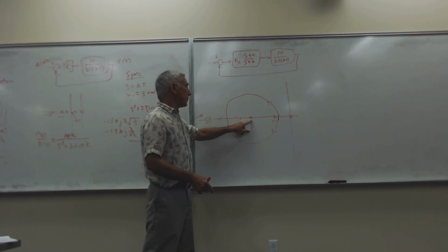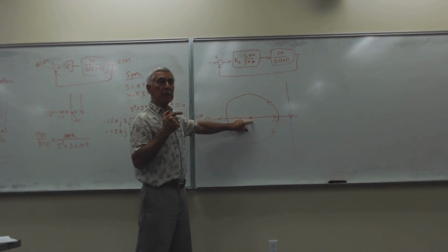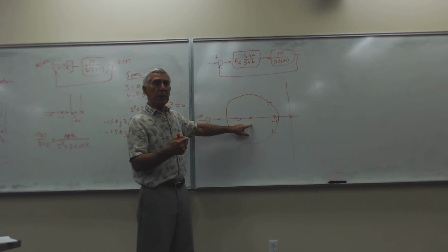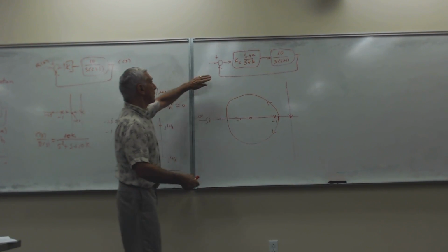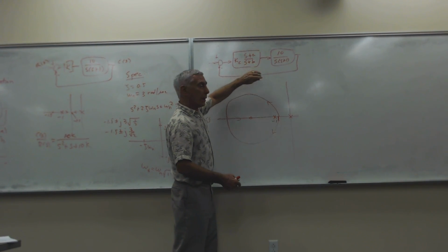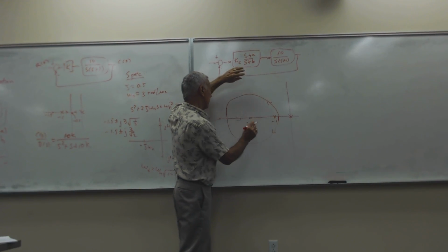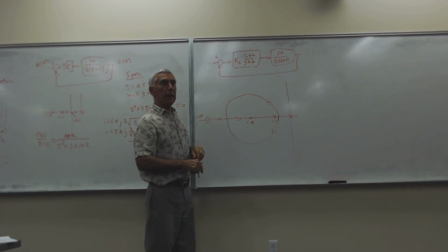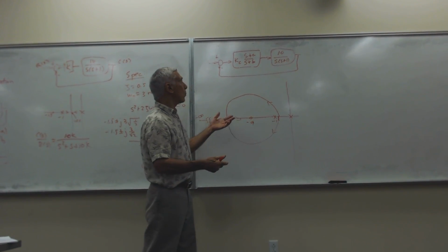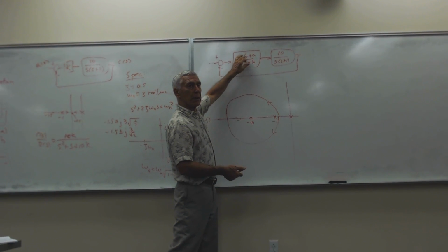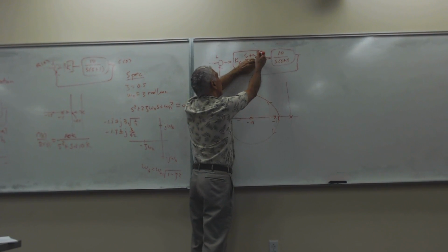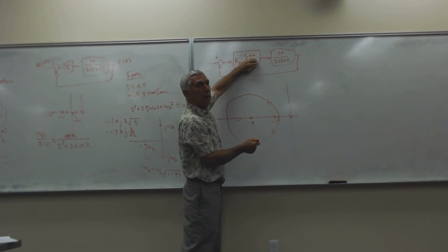So that is if you use a single proportional plus derivative, as if you had only this here, and this is minus a. And so that would work. However, we want to use this form here, right? The lead compensator. This form here is proportional plus derivative, PD.